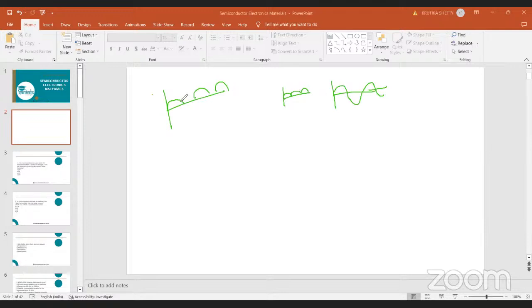What happens in case of half wave rectifier? Only half of cycle is getting converted into DC. This is half wave rectifier. What happens in case of full wave rectifier? The entire AC is converted into DC here. The difference between half wave rectifier and the full wave rectifier is, in case of half wave rectifier we are using single diode, and in case of full wave rectifiers, we are using two diodes here. Okay, this is regarding the half wave and the full wave rectifier. We don't need much more explanation here, because in MCQs there is a chance they will ask you questions only on this.